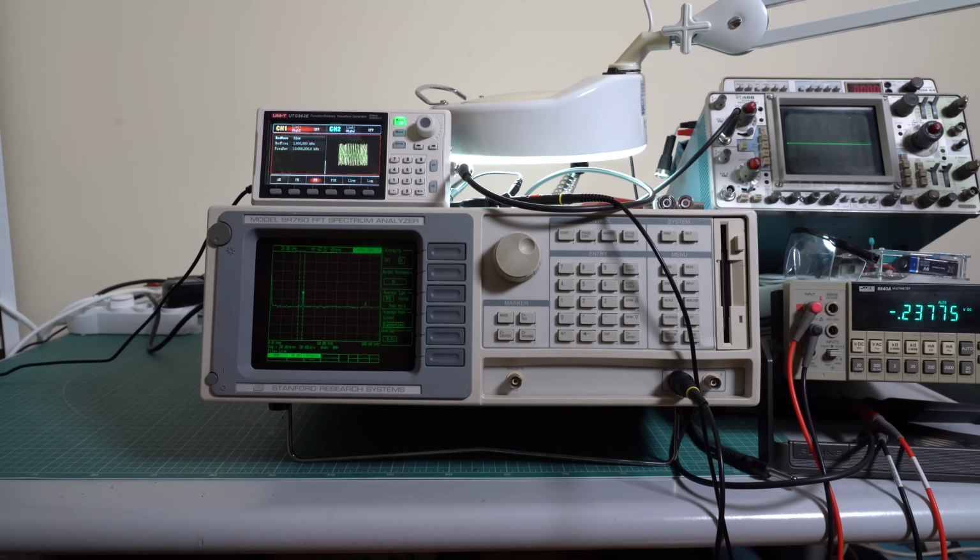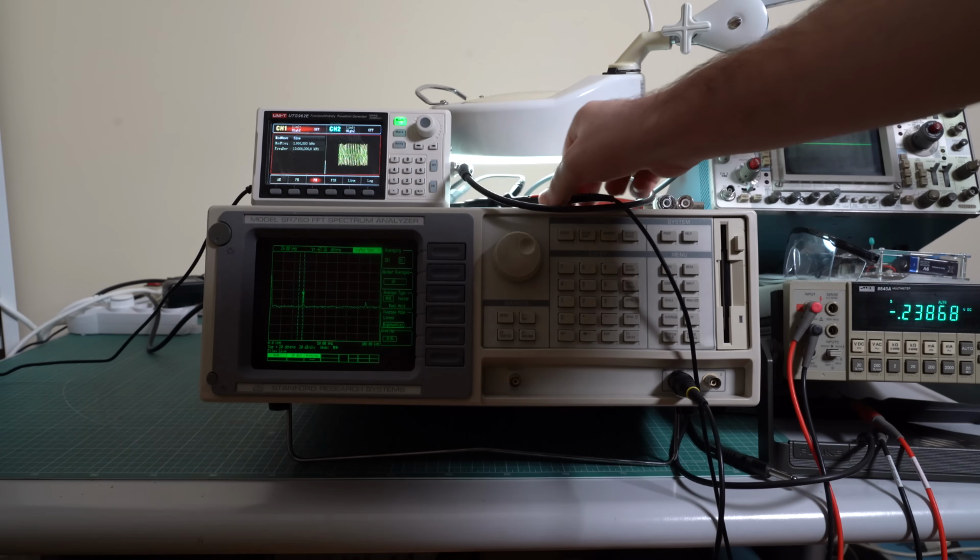The spectrum analyzer can also be used for EMC compliance. I know, it sounds like we are repeating the previous topic, however that's not the case. Because don't forget that there is a class of devices called unintended radiators, meaning that some devices emit radio frequency noise as a side effect of their operation. And I can also demonstrate this really easily.